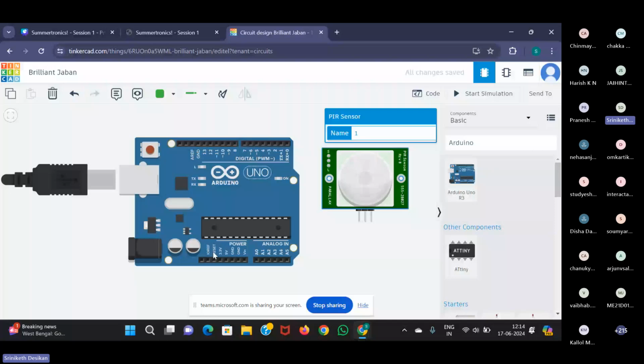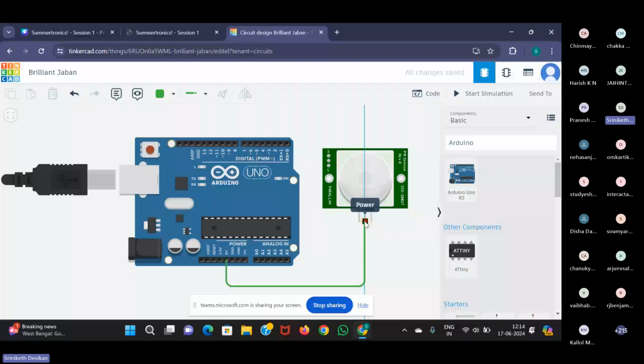Right here, we want a 5-volt power supply, which is what we generally use for VCC. We have pins here for 3.3 volts as well, but we'll go ahead and use 5 volts, and let me use a green color for 5 volts, with my convention which I stuck with earlier. Let me connect it to power. This will deliver power to the IR sensor as well. The microcontroller will deliver the 5-volt power supply, but to complete the circuit, we obviously need to ground it, and we have 2 ground pins right here.